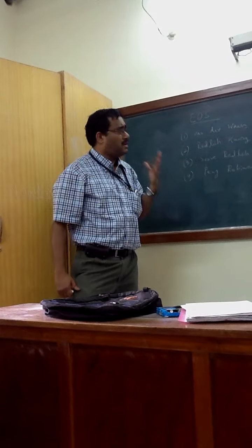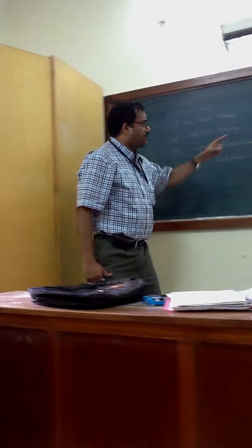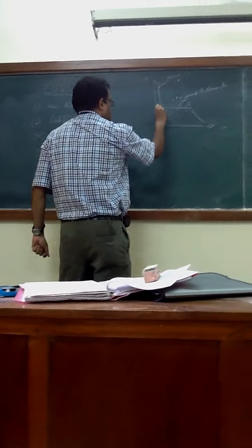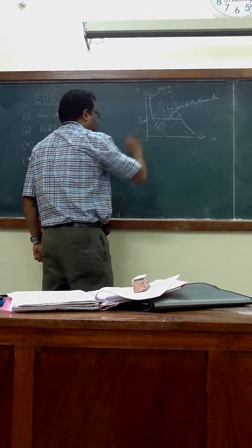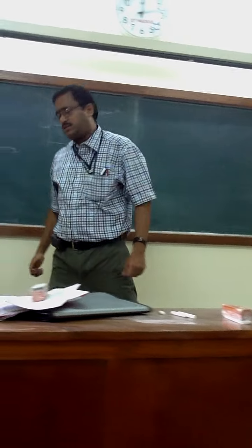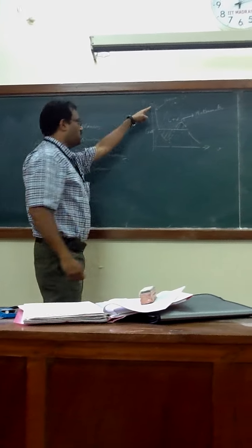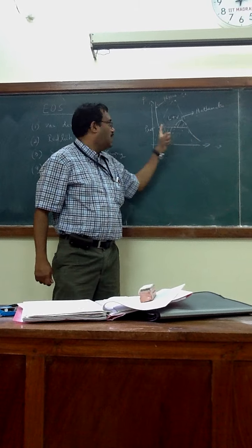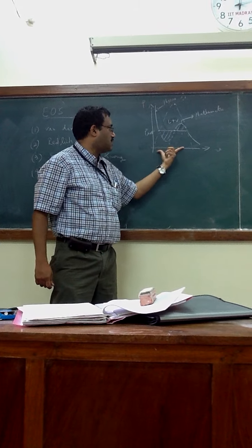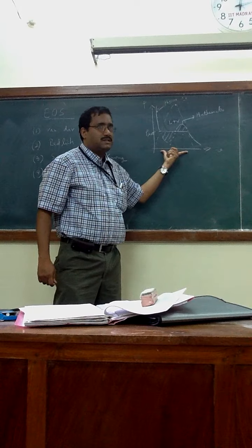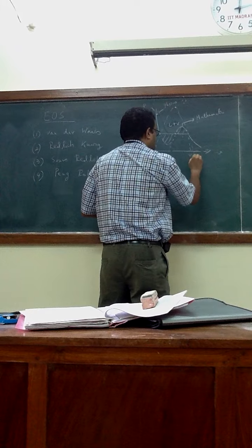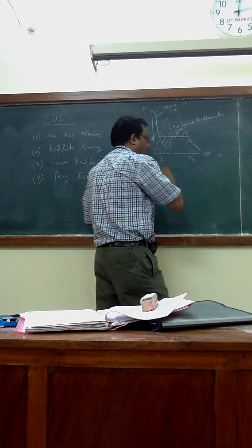But now, if you have a liquid to vapor transition, you know the phase change occurs here, so all you need to know is the saturation pressure, Psat. The saturation pressure is known. Then you can say this is my initial pressure, this is my Psat, and from Psat to these branches as gas phase. So here you use liquid phase property, here you use gas phase property, and in this zone where your pressure is constant, the work done is Psat times Vg minus Vf. This is Vg, this is Vf.